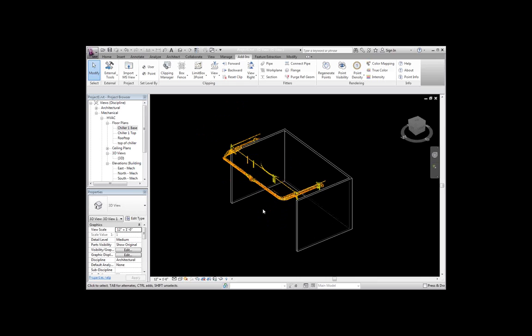So that's a few of those tools that are specifically built for Revit, working with the point clouds. We have the ability to fit work planes to a surface of the point cloud, so you can then start working on a work plane. We have the ability here to fit sections. So if you have a slice of the point cloud and you want to do a building outline, you can do a rough outline of the building and have it fit that linework to the point cloud itself.